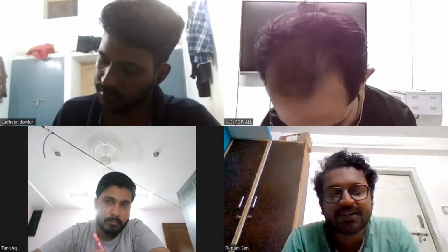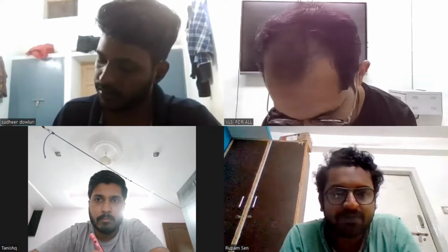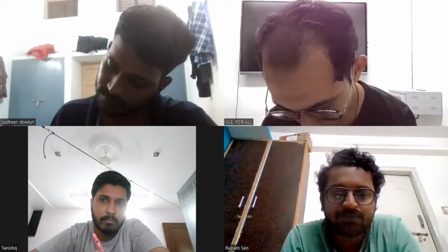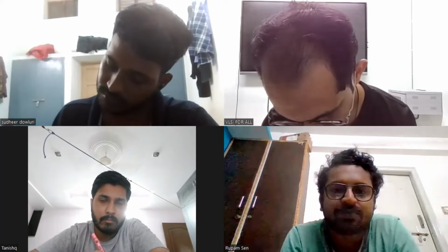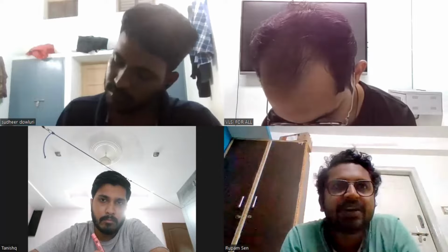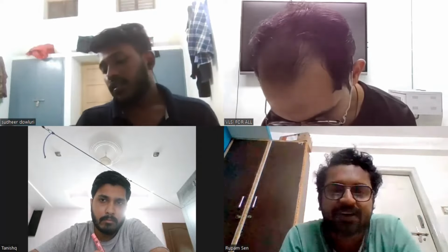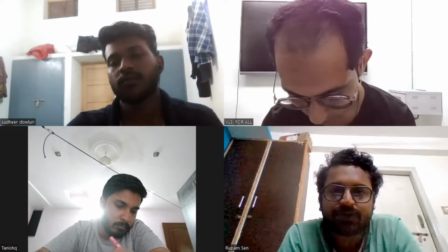I took the select line as A, my input. So if I put A equal to 0, it will select I0. In I0 I can give one variable, like B, and in I1 I will give B bar. So when A equal to 0, I will select B, and when A equal to 1, I will select B bar. Then the output will be the XOR gate.